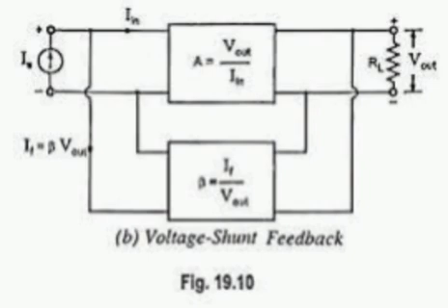Common source amplifier is equivalent to the CE amplifier of BJT. Common drain amplifier is equivalent to the common collector of BJT. Common gate amplifier is equivalent to the common base amplifier of BJT. Common drain amplifier is also known as source follower. Common gate amplifier has unity current gain, low input resistance, high output resistance, and high voltage gain.